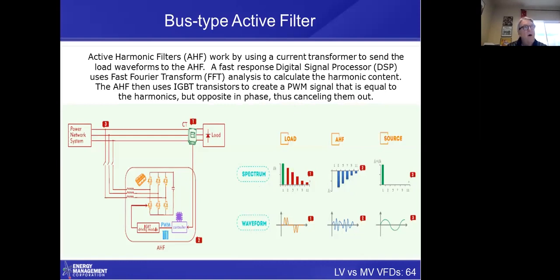But guess why all of that technology is necessary? All of that technology is necessary because low voltage drives have very poor harmonic performance. And therefore, there are various types of technologies in order to clean that up. You don't need any of those technologies with a really quality medium voltage drive because it doesn't generate those levels of harmonics. And therefore, you don't need any of these technologies.